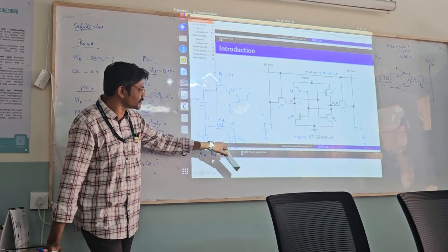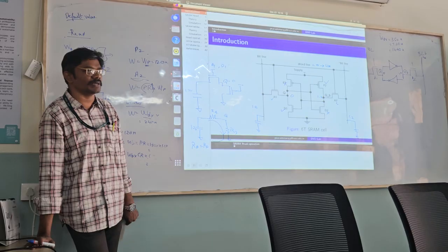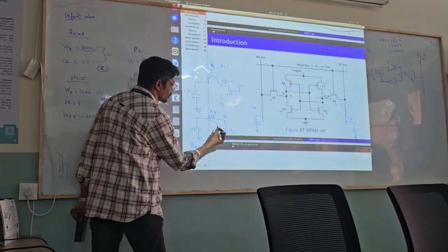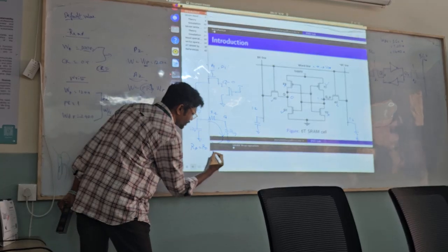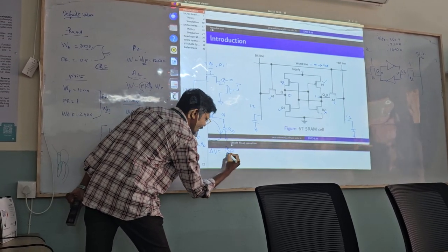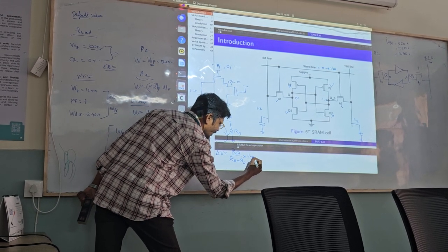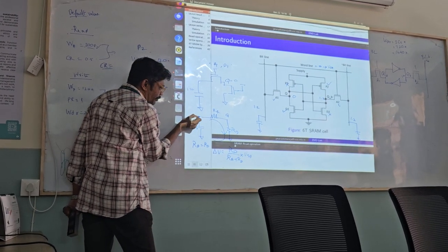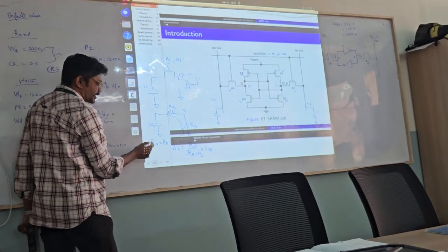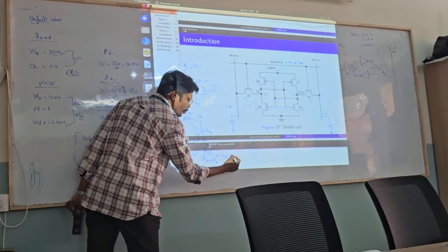What is this resistor forming across this supply of 1.2? It's a voltage division rule, right? So based on the voltage division rule, if I assume that there is a change in the voltage, which I monitor as delta V, then I can write it as RD divided by RA plus RD times the supply that I have here across the input. Now, under the assumption that both the resistors are equal, this voltage will be close to 0.6 volt.